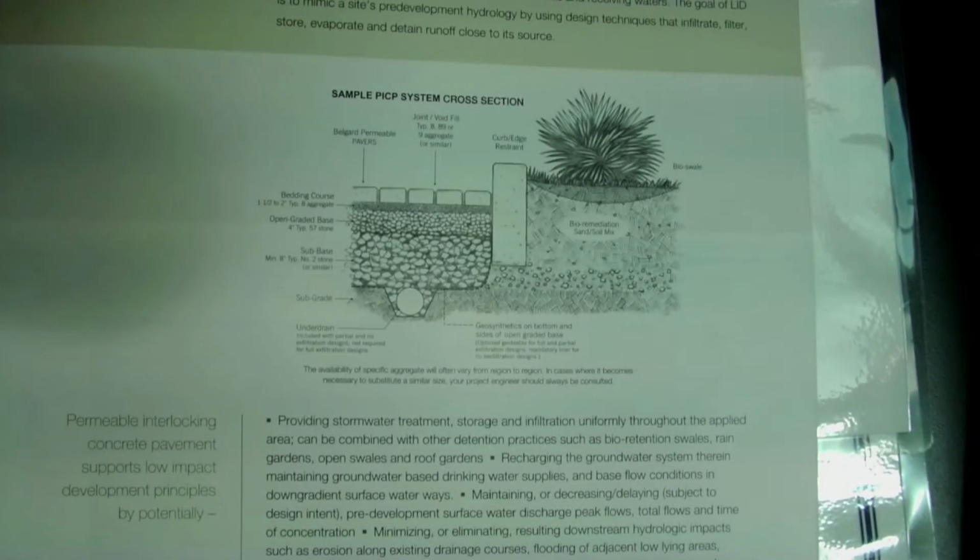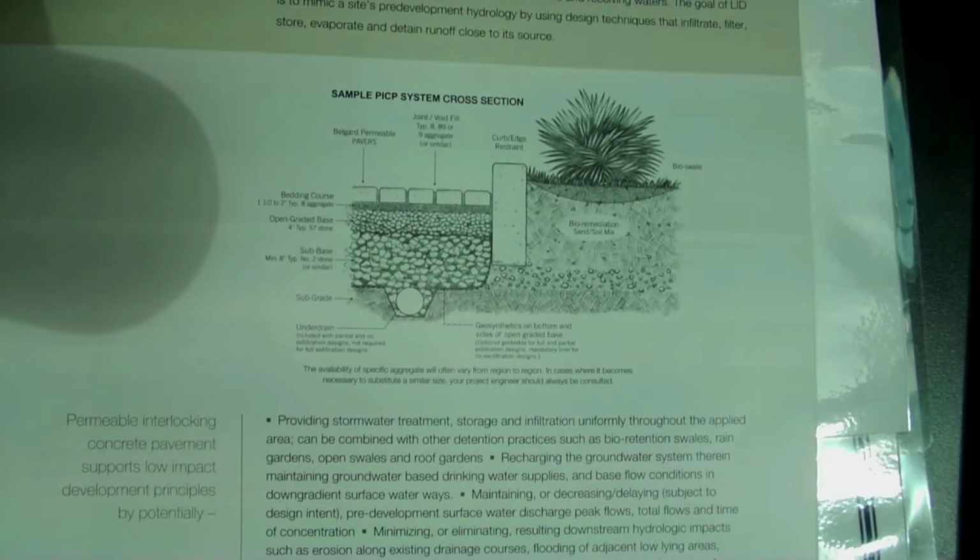But basically, the base inspection should be no different than if you were paving a street. Same part, before you put the asphalt on, because once the paver's on, it's over with. Essentially somebody could take a half a gallon of water and pour it out, and if it runs off, then it might not be in there right, and if it goes in the ground, you're pretty well there.